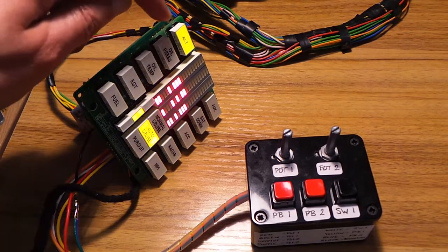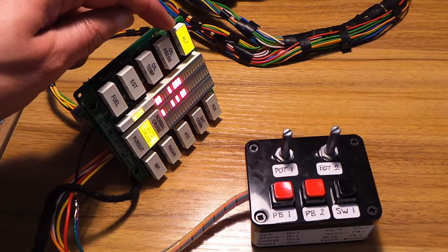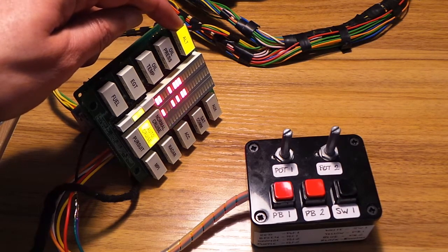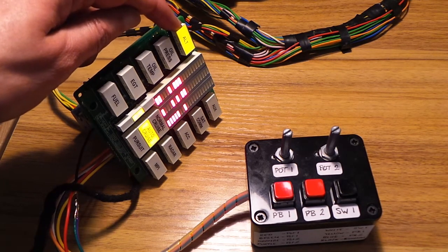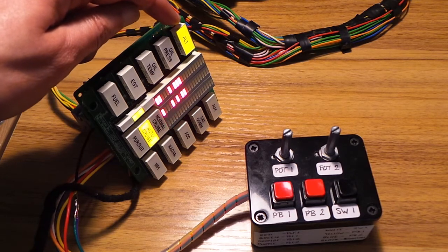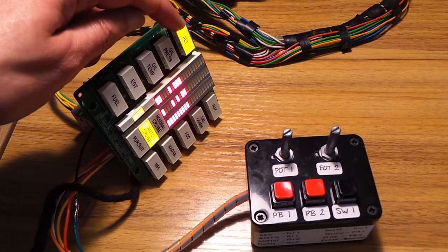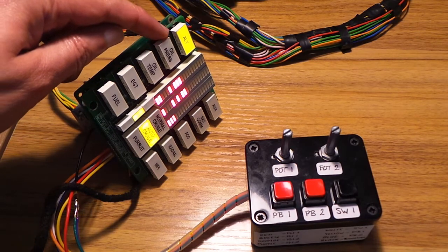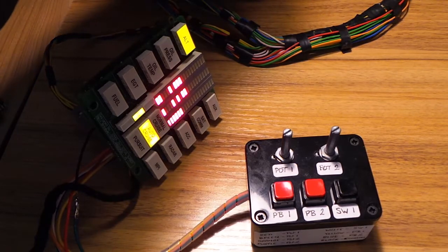These indicators down the side indicate the power supplies. Now on this rig, the primary ignition power, that is the power that comes in on pin 2, is connected to the power on pin 1, so that's on all the time. But if you had a separate power supply on the I1 input that we mentioned earlier, that would be indicated on that top LED on the left hand side. The secondary ignition power is hooked up to this second LED, so if I put that on, you can see that responds to that one.